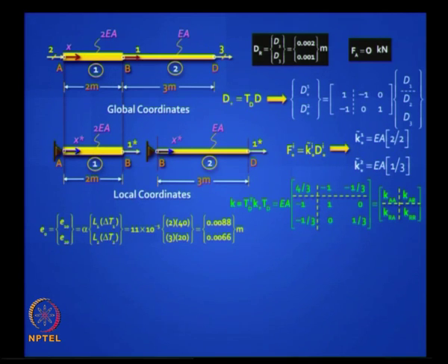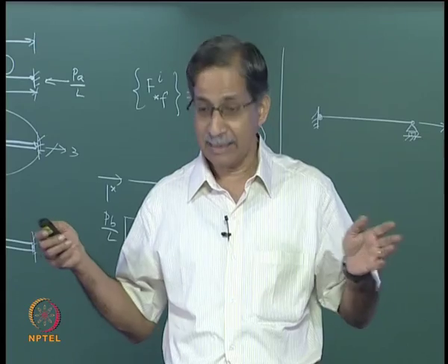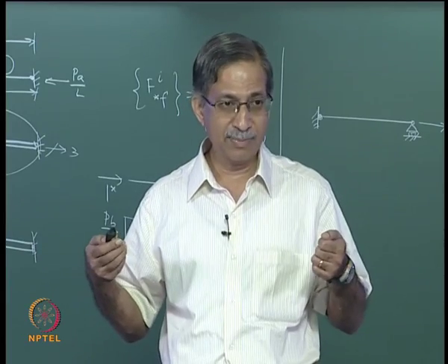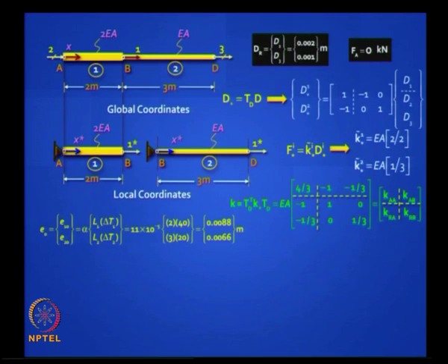First find out the free elongation L alpha delta T, right, and that elongation is fully prevented in the primary structure. So is this step clear? You get that much, that is E naught. Now if you have a lack of fit problem, you get E naught directly, you do not have to do this step of L alpha delta T.